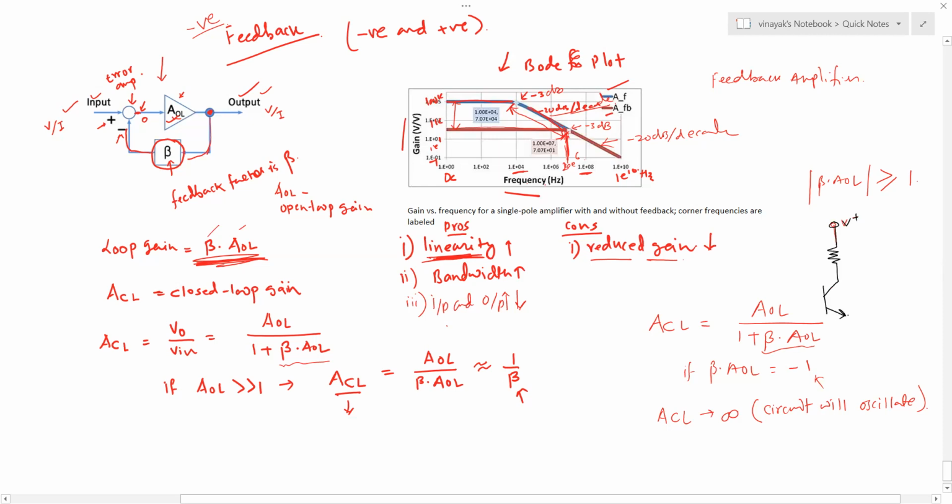Then you have this transistor, that is NPN, and then you set the bias, depending on what kind of biasing method you use, collector to base bias or fixed bias or voltage division bias, etc., so that you maintain the VBE here that turns on the transistor, and then you take the output here.